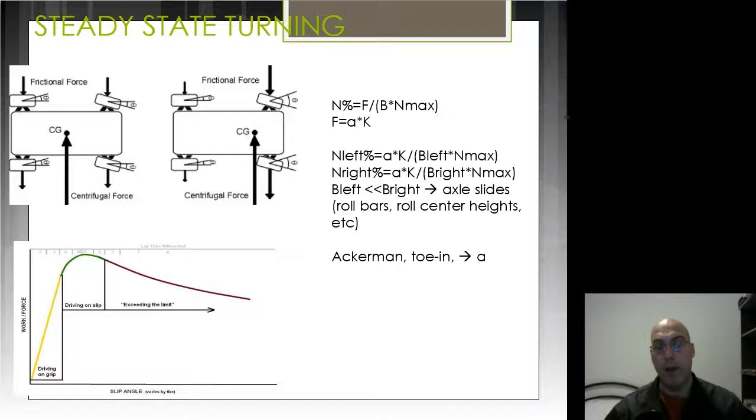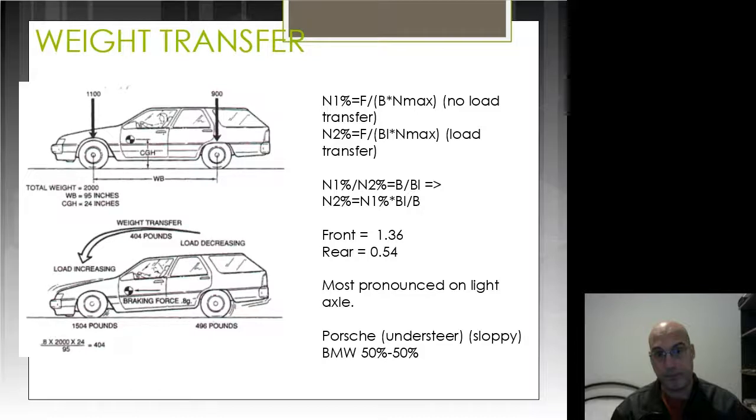The other thing that we look into is weight transfer. I have here this vehicle. What we need to remember about weight transfer is that obviously the lighter axle will slide sooner. But the weight transfer affects the axle that is lighter, that's far away from the center of mass, that is lighter anyway, even in a static situation.